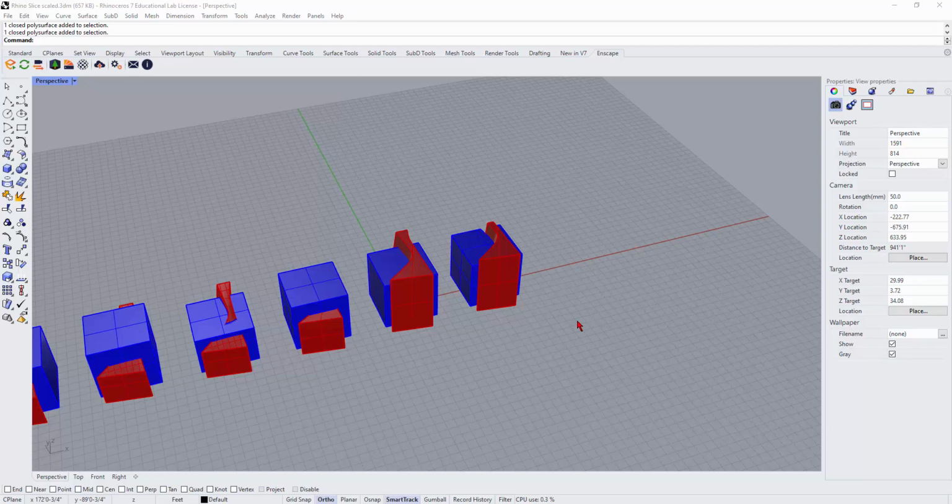We're going to export some masses from Rhino as DWG solids to link into Revit, and use them to make walls, floors, and roofs, and for representation purposes. So basically you're going to need a closed polysurface.